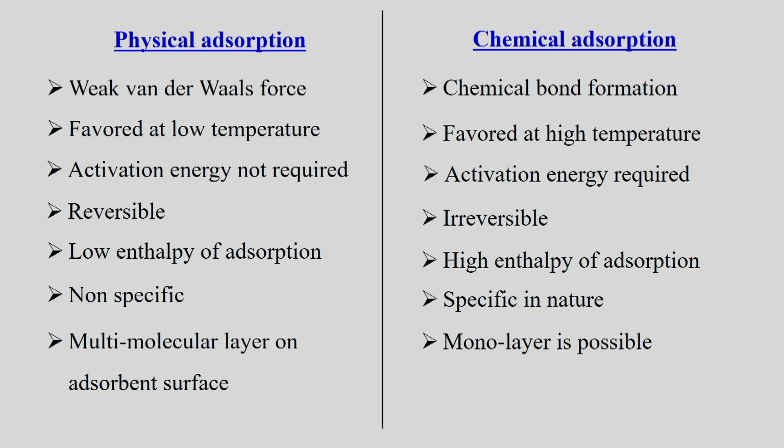Activation energy is not required at all for physical adsorption, it is simply the addition of the target component on the adsorbent surface, but activation energy is required for chemical adsorption. Physical adsorption is highly reversible, but chemical adsorption is irreversible in nature. Low enthalpy of adsorption is there for physical adsorption, but high enthalpy of adsorption is there for chemical adsorption.